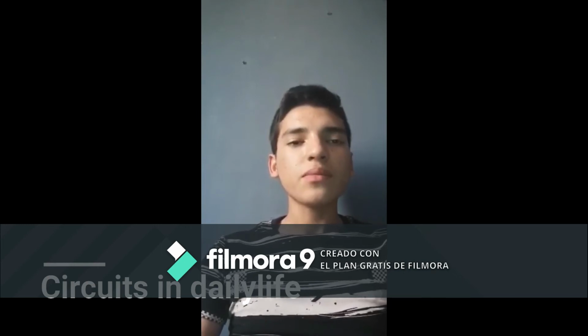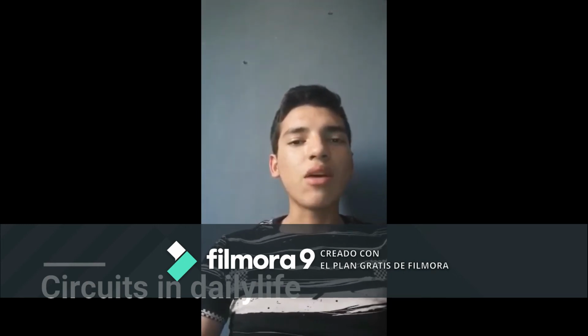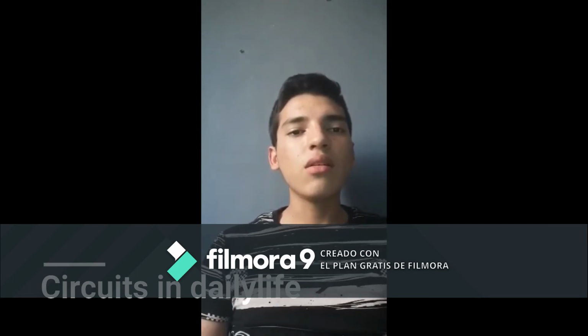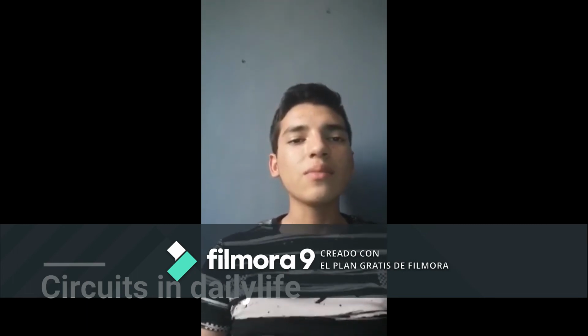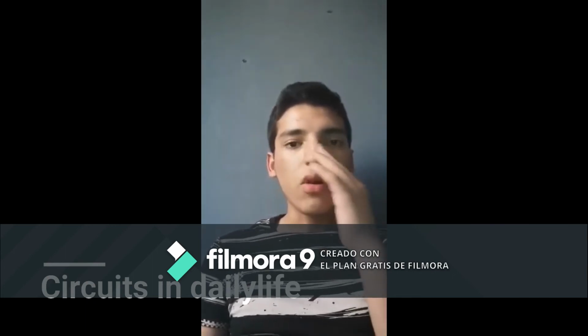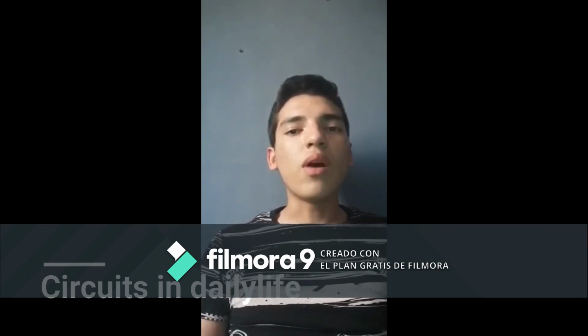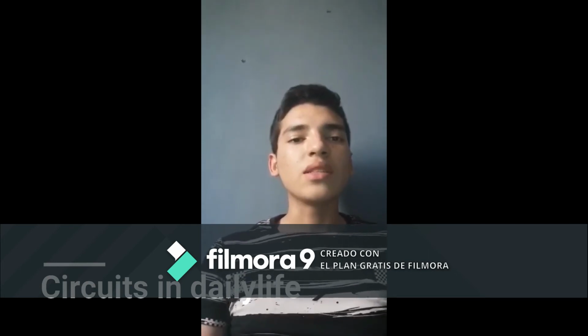Admittedly, it is not a daily life example, but more like one in 365 days. I mention Christmas lights as a good example because many people struggle each year with taking the lights out from last year, putting them on the tree, and discovering that a quarter of the lights don't work. This is generally down to one defective bulb that has several series connections that connect a group of bulbs.